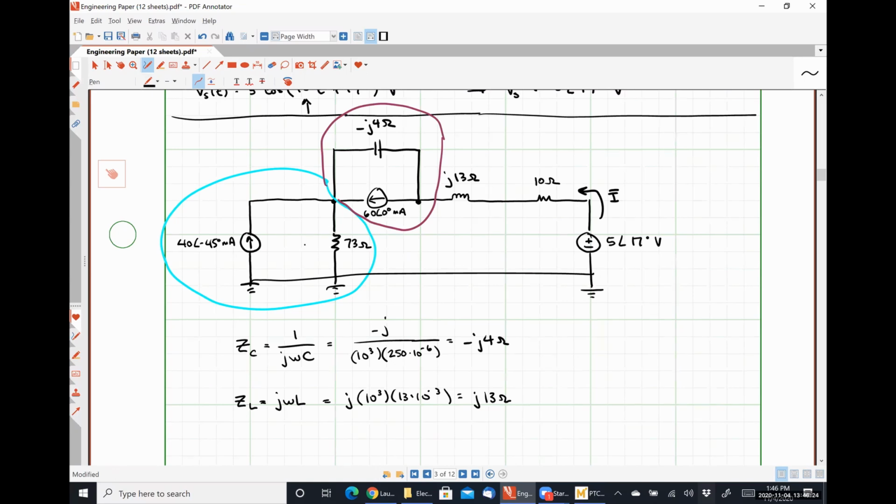And if I turn on this current source here and turn this guy off and short circuit this guy, current division will give me an answer. And again, the exact same thing with this guy on, this guy off, and this guy off. I again have a way that I can just do current division. But I think the source transformation route is going to wind up being the least amount of work. So that's the way that we're going to go.